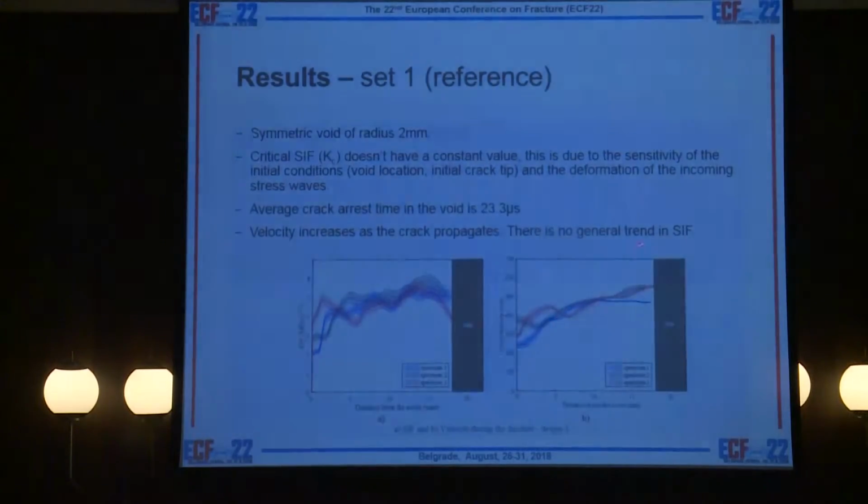And this is the crack propagation velocity. As you can see, there is a general trend of velocity increasing as it approaches the void. And the average crack arrest time in all these 3 cases is 23.3 microseconds.